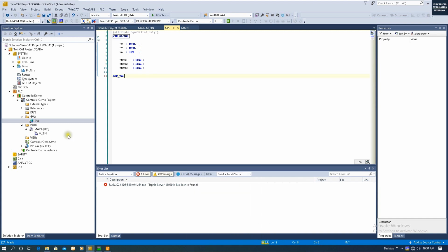Then from the OPC UA client side, they can update and browse the newly added variables. If you have a better way, please let me know. From the couple of projects I did before, I found this is the best way to guarantee the new variable can be updated. Because in some cases, the new variable may not be updated successfully. Then you have to shift back and forth and refresh your provider tag list. It actually costs more time than this way.